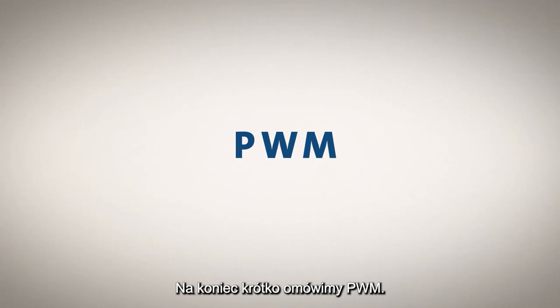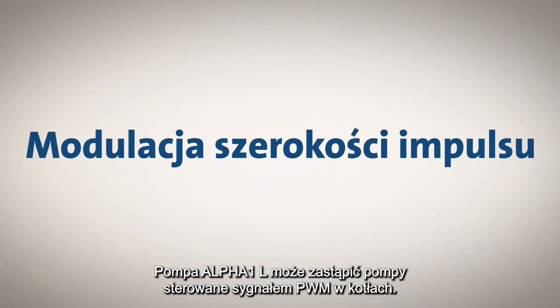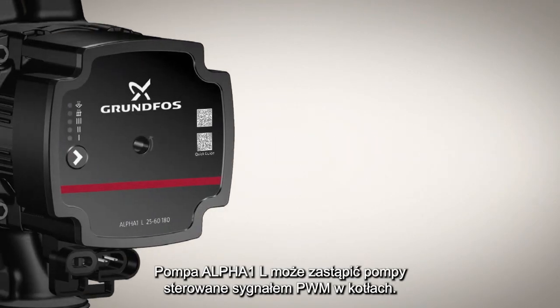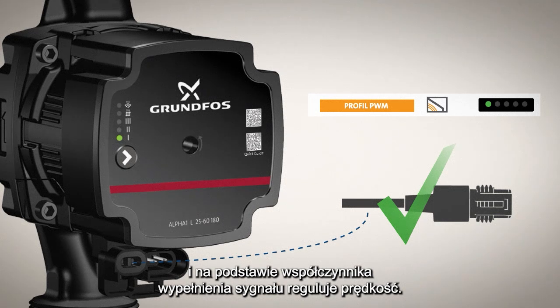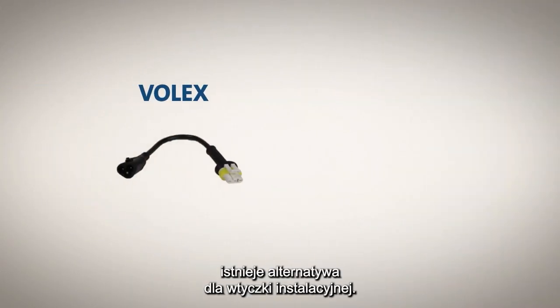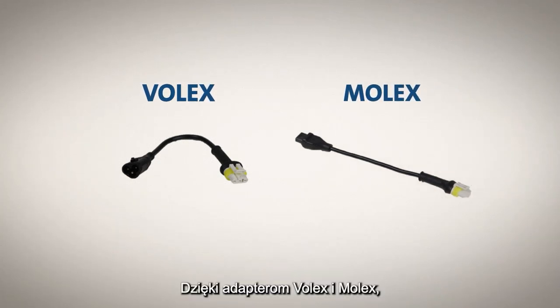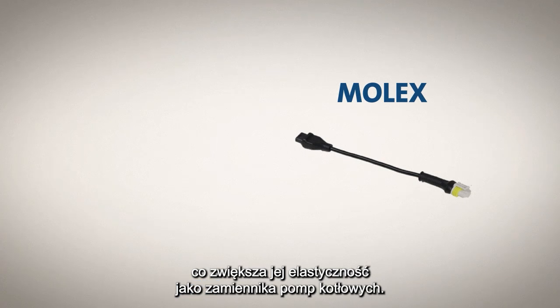Finally, we are going to briefly touch upon PWM. PWM stands for Pulse Width Modulation. The Alpha 1L can replace pumps controlled by a PWM signal inside boilers. The pump receives a PWM signal and, based on the density of the signal, the speed is adjusted. When it comes to power supply, there is an alternative to the installer plug. By using Volex and Molex adapters, the Alpha 1L pump can be connected to boilers using this type of connection, improving the flexibility of the Alpha 1L.